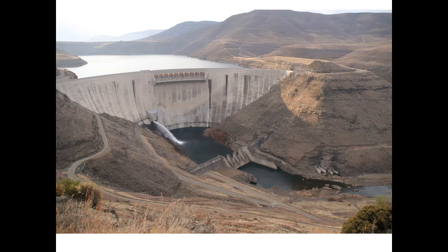And then you know that as cement cures, it's an exothermic reaction. So on this side of the dam, right outside of the picture, there was a huge building, which was essentially a slush puppy machine as big as a rugby field. And this slush was pumped through the concrete while it was poured, to keep the temperature below 32 degrees centigrade in order for the concrete not to crack.